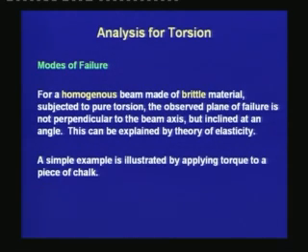If we take a piece of chalk and try to apply a torque in the chalk, then we can observe the failure plane in the chalk piece. This failure plane is not a planar surface, and it is not vertical to the axis either. It is a curved surface which is inclined to the axis of the beam.